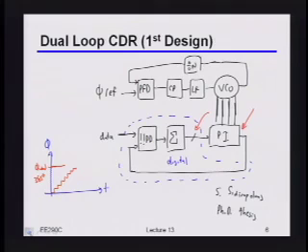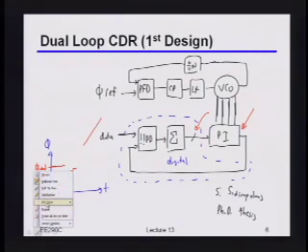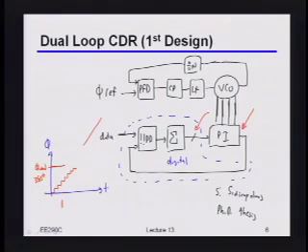It's got an infinite number of bits of resolution, but I want to know what happens if you feed a phase ramp into that kind of CDR. So what's going to happen? You'll end up with a static phase offset. Yeah, you'll end up with a static phase offset.